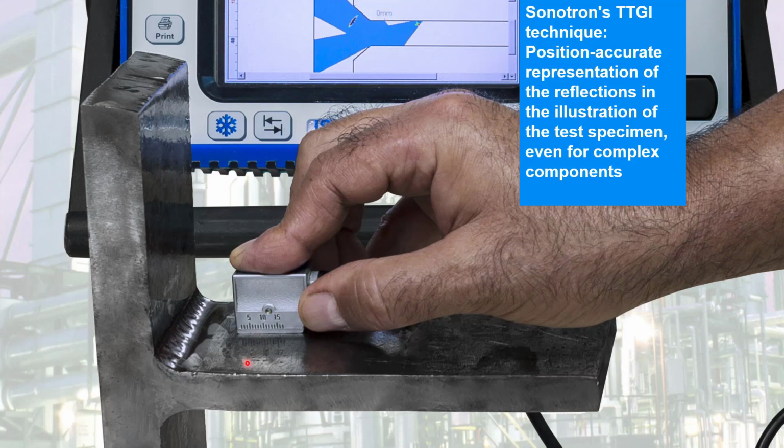When you move the probe parallel to the weld in that direction, from here to there, you inspect the whole volume. Whatever is blue here is the area which is covered during the scan. And if there is a reflection, a flaw, you get an indication here. It's a range from the lower angle, which reflects from the back wall up here.